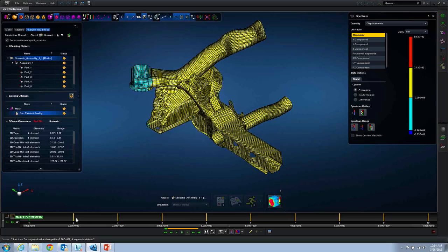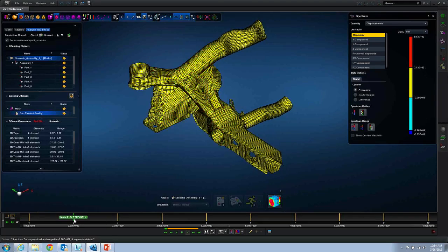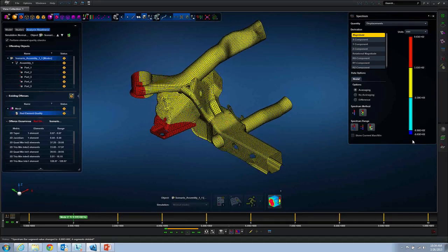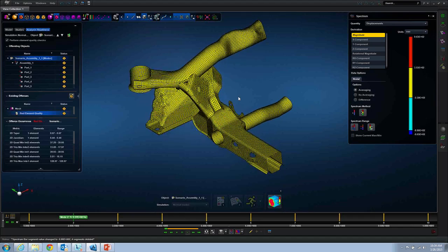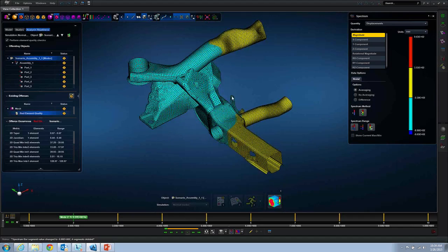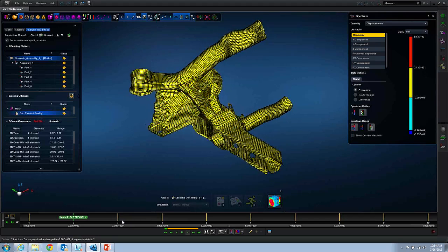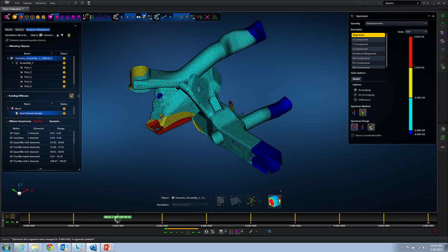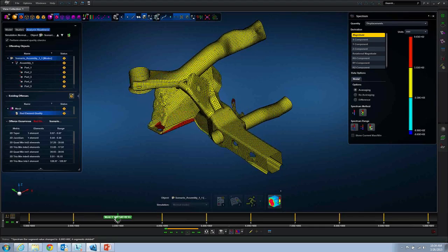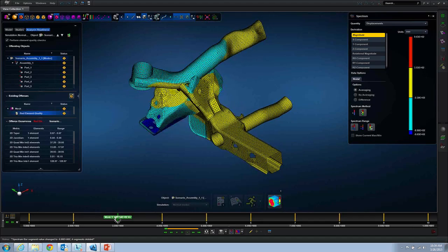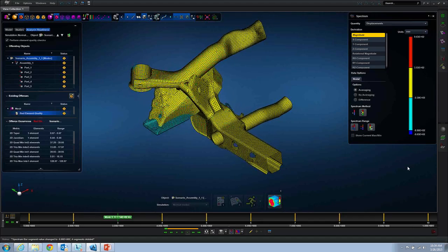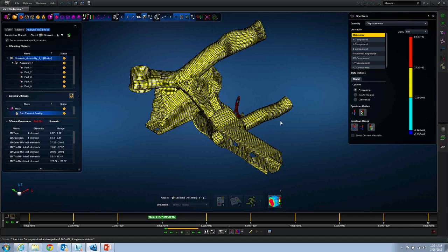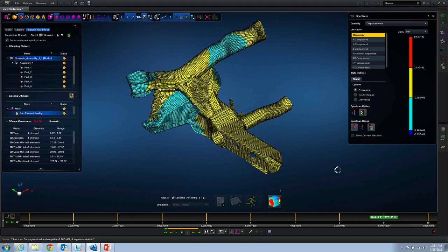After that, if I navigate to the second mode, it is showing the modal behavior and eigenvector with respect to the locked condition. That means you should be able to identify in which area the eigenvectors are more dominant or more participating, or whatever the case may be. I think it is left to your imagination how you would like to slice and dice the results interpretations. And likewise, if you were to do two linear static analyses, and if you lock the baseline analysis contour, you can plot the second time around so that you can compare the two different runs, right? It is as simple as that.